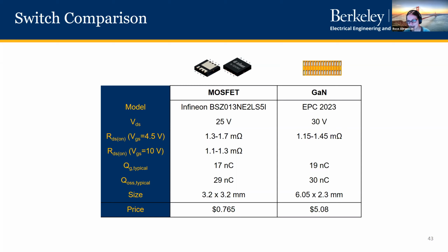Yeah. What is the startup sequence? Is there a startup sequence, Rose, for your power? No, there's no official startup sequence. We do ramp up the voltage manually for the converter while the gate signals are already running. So that might be something to look into in the future, but as of now, we just do it manually.